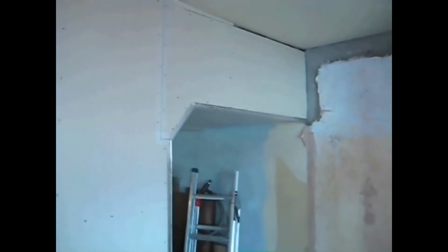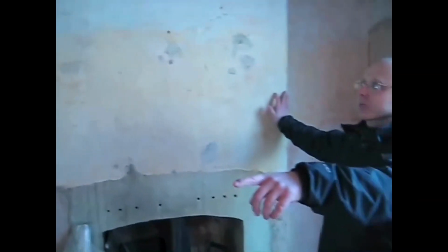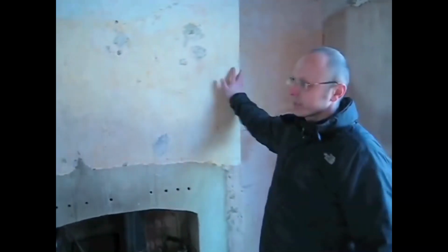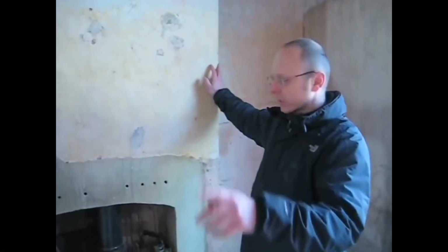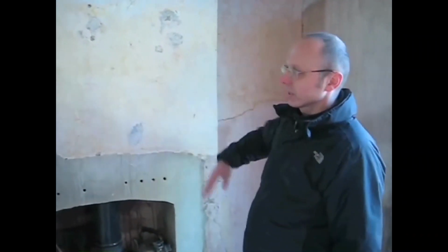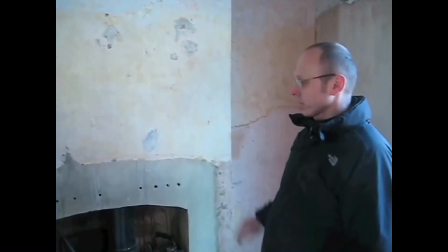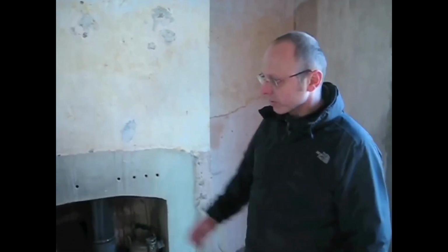Then we'll probably go on to, whilst I'm doing that, Tim will probably be doing his angle beads. No, in fact, I'll be doing them. Tim will be doing something else. We'll probably go straight onto that wall, get that out of the way. In the meantime, while that's setting, starting to go off, we'll put angle beads on here. We'll level this up with bonding. When that goes, I don't think we've got any. Oh, we've got some cement.